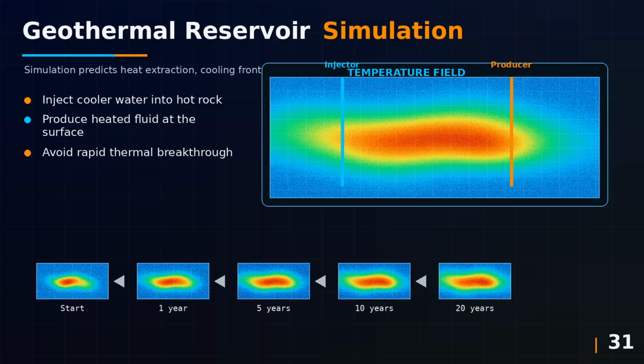In geothermal systems, a key risk is thermal breakthrough. If cold injected water reaches the production well too quickly, produced temperature declines and the project becomes less efficient. Therefore, well spacing, flow rate, fracture connectivity, permeability, and reservoir temperature are very important.